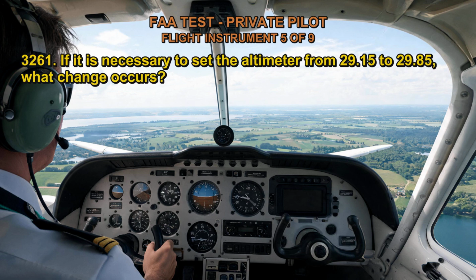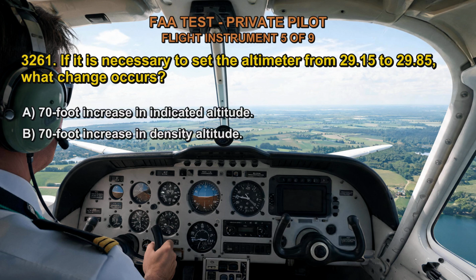3261. If it is necessary to set the altimeter from 29.15 to 29.85, what change occurs? A. 70-foot increase in indicated altitude. B. 70-foot increase in density altitude. C. 700-foot increase in indicated altitude.